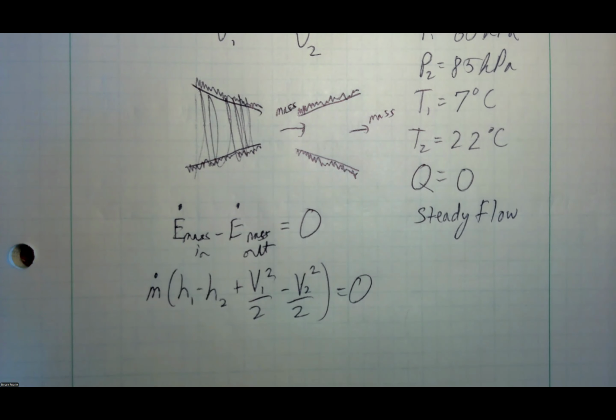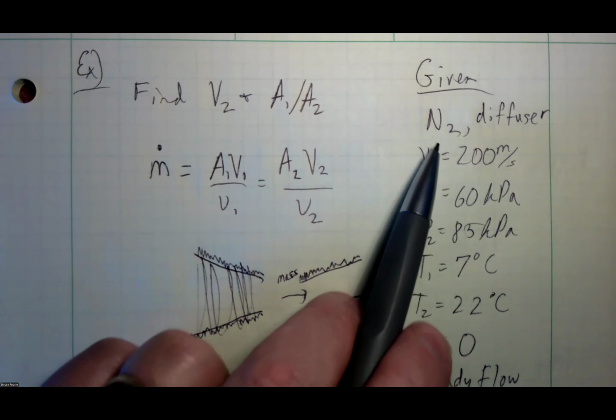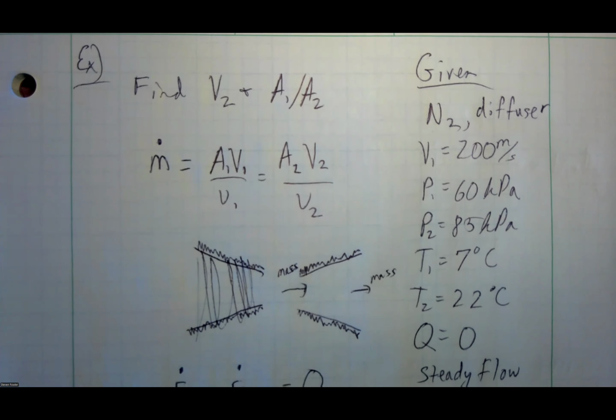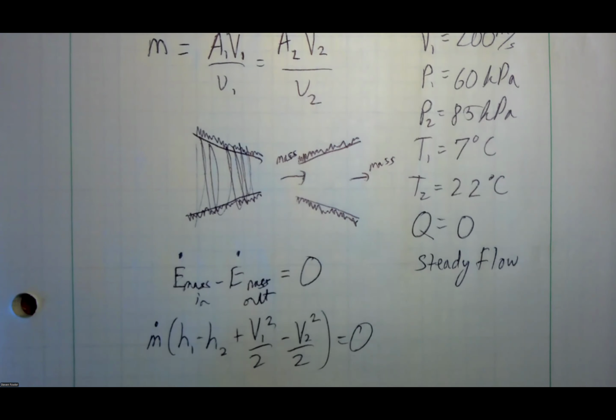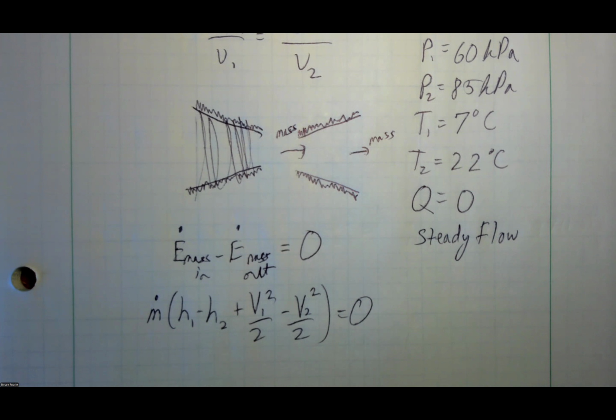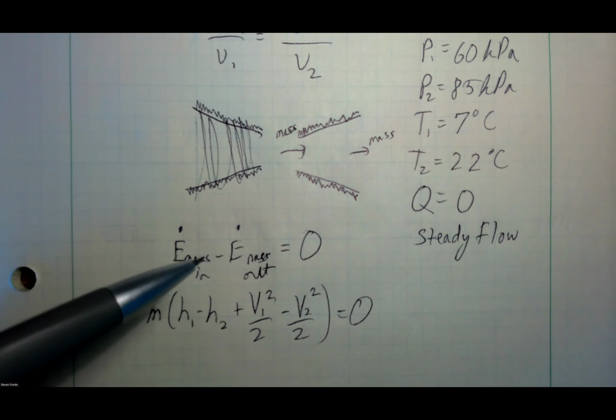If you don't have that memorized, that's okay, but you do need to get to where you understand that process flow of how do I find a property? Well, I need to know the substance. It's an ideal gas. Okay, I need to use rules for ideal gases. If it's water or R134, I need to use the rules for using property tables. If it's solids or liquids, I need to use the rules for solids and liquids accordingly. Okay, that's kind of how that process works. What's the property? Well, what's the substance? Okay, follow the rules for that substance.